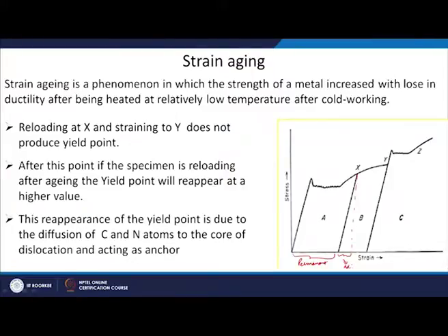So, whenever I stop the deformation, the total strain will not be the one I get by drawing a perpendicular line to the strain axis. There will always be some strain which is recovered, and this phenomenon is called spring back. I forgot to tell you this earlier, which is why I am bringing it up here now. Why it is important is that when you are doing deformation and you remove the load, some of the deformation will be recovered.